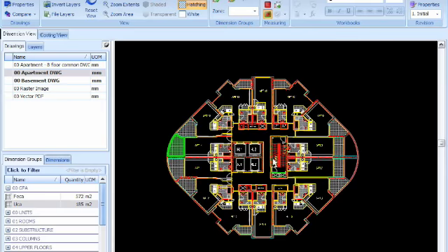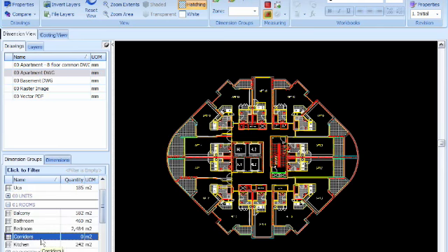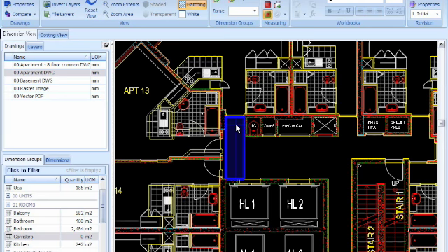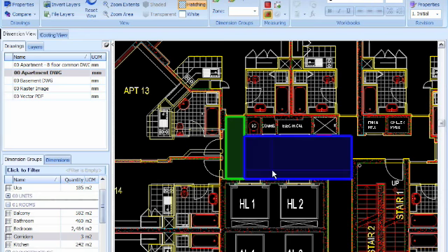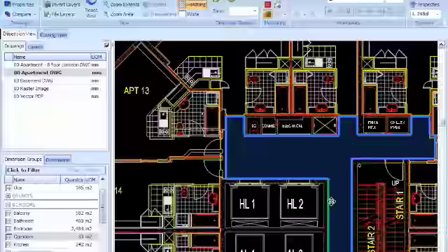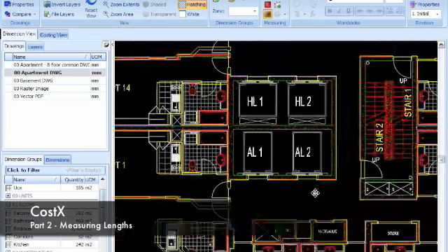There are other ways that we can measure areas from these drawings. For example, if I now select a corridor dimension group, which I have in my template, I can go and measure the corridor of this floor plan. We have another method which we can utilize to measure quick areas. Anything that's a four-sided area we can pick up with what's known as a quick point. As you see here, it's measured that area, a four-sided shape, and we can measure these four-sided shapes and combine them together. So quickly and easily we can measure this corridor.